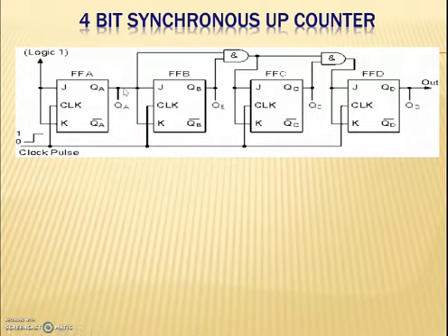So for 3, QA and QB must be 1, 1. Only after that QC must advance to 1 and correspondingly the last flip-flop also must respond, and only when all QA, QB, QC are all 1, then it will proceed to 8. Likewise it goes. The additional AND gates here generate the required logic for the JK inputs of the next stage.